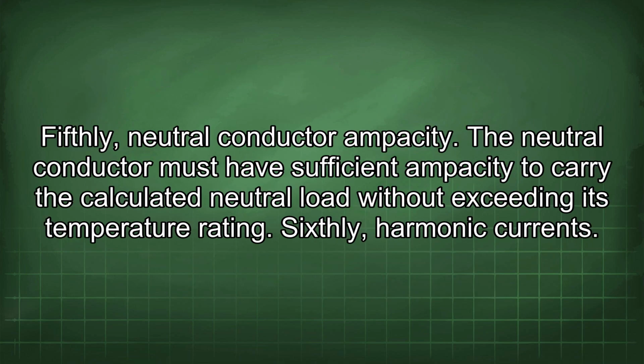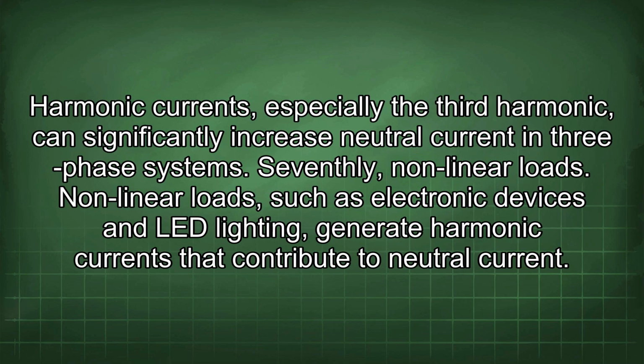Fifthly, neutral conductor ampacity. The neutral conductor must have sufficient ampacity to carry the calculated neutral load without exceeding its temperature rating. Sixthly, harmonic currents. Harmonic currents, especially the third harmonic, can significantly increase neutral current in three-phase systems. Seventhly, nonlinear loads. Nonlinear loads, such as electronic devices and LED lighting, generate harmonic currents that contribute to neutral current.